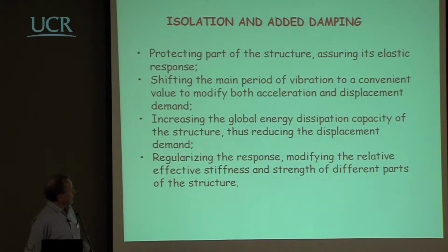And the second point there, which is shifting the main period, we have to underline, modifies both acceleration and displacement demand. And to keep the displacement demand within reasonable limits, you increase the global energy dissipation, and this means reducing the displacement demand.